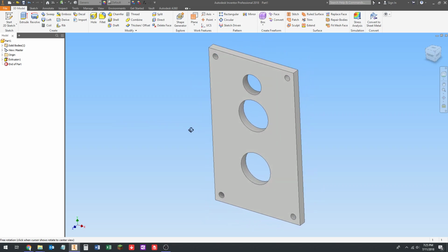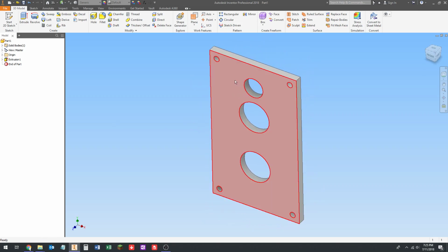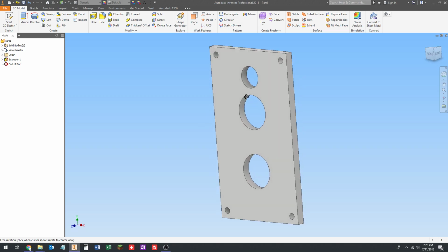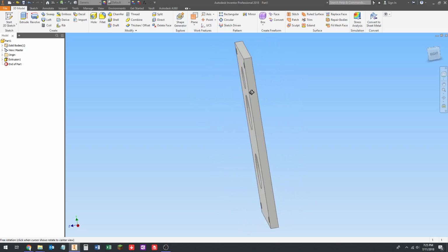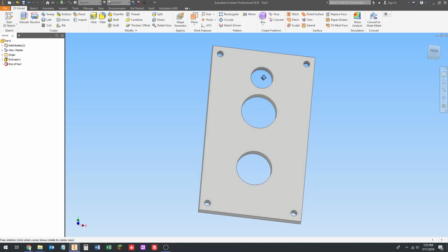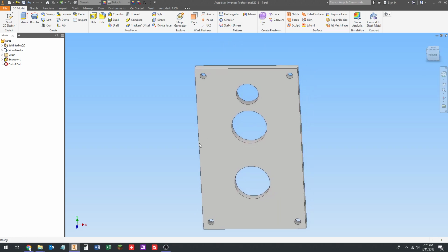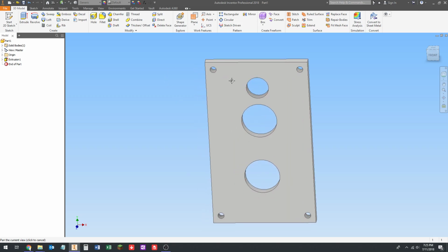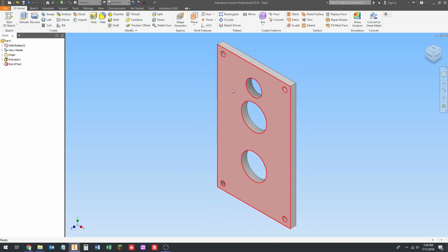The motor has 2 threaded holes. What we're going to do is put the boss of the motor in this hole, and then thread 2 screws in from the outside into the motor. So we need to have those holes. I'm going to place another sketch down on the front of this part using the Start 2D Sketch tool here. I'm going to click on that, and then click on the front face of this gearbox.